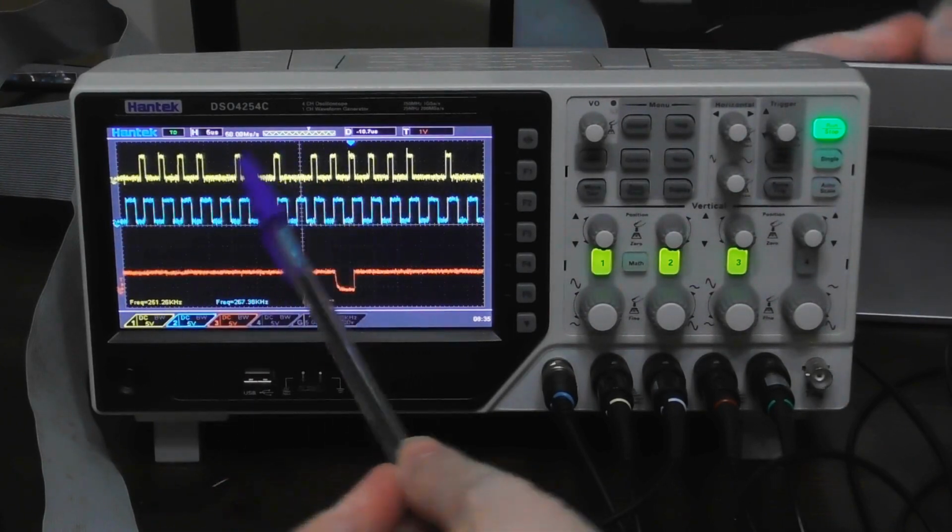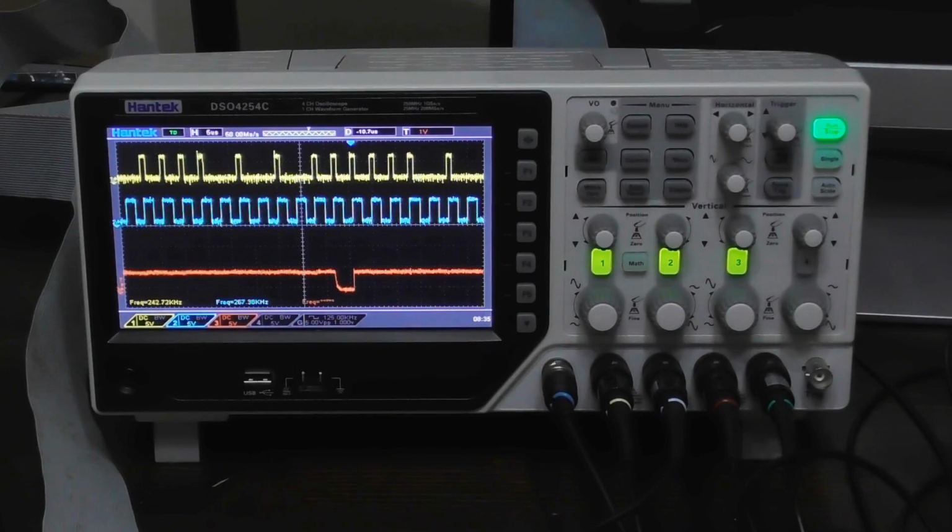and those are FE and FB in the data part of the signal, and FE indicates that the upcoming block is a sector ID chunk which contains the track, head, sector, the length code and a CRC, while FB indicates that what's about to follow is sector data for whichever sector had the previous ID chunk. And FB would then be followed by just a whole bunch of actual data bytes on the disk, and a CRC at the end as well.